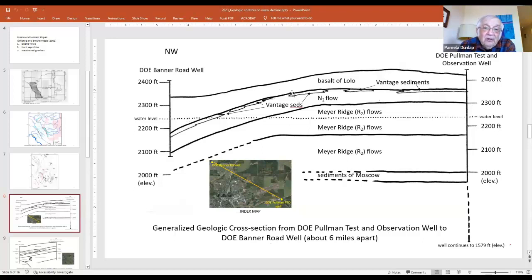We know the water moves down the slope of interflow zones, down the dip. So if you were at this point, at the water level, you lower that 40 feet, what you've done, now you have less of the interflow zones that have water running through them. And that means that you have decreased the number of discharge areas as time goes on. So I would suggest that here's a geologic control on water level decline, because if you decrease discharge, you're also decreasing the potential water level decline.